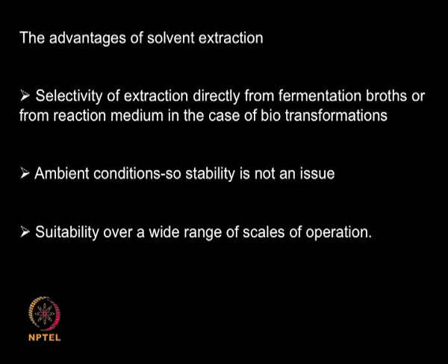Advantages of liquid extraction: you can very selectively extract a particular metabolite or protein. So by selecting your solvent or aqueous phase, selectivity can be tremendously improved. It is done in ambient conditions, so stability or instability problems is not an issue, and we can use it at a wide range of scales. As I said, we can practice these in your lab, or you can take it to thousands of liters scale in an industrial setup as well.